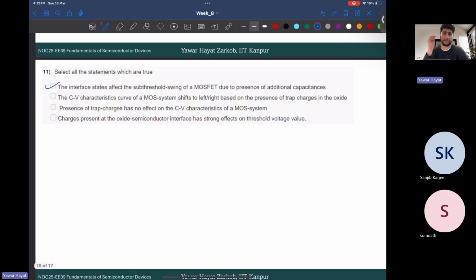Was subthreshold swing introduced in the lectures that you saw? Okay, sir, got it. I can still explain. See, your subthreshold swing is kT by q, and there is an ln 10 factor as well, right? So it's 2.3 kT by q times n, where n is your slope factor, right?